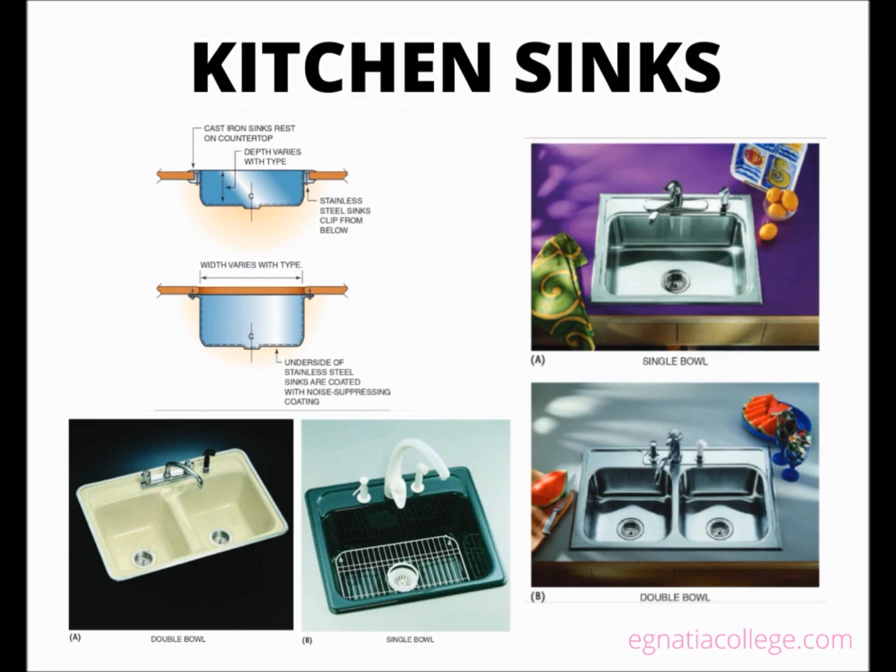Surface mounted sinks, also known as self-rimming sinks, are manufactured with holes for installing the faucet directly onto the sink. Holes must be drilled into the countertop surface to install faucets for most under-counter sinks. A kitchen sink is usually installed in a standard width cabinet known as a sink base. The piping serving the sink is typical for most sinks.